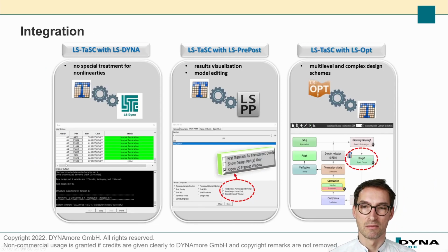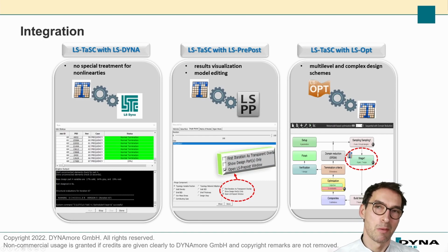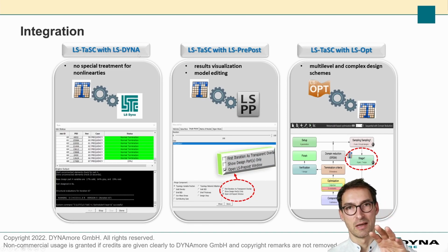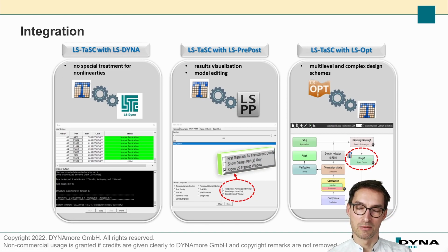LS-TaSC is integrated very well with LS-DYNA because it's the same company, of course. Then we have a very good integration. So LS-TaSC works with LS-DYNA. So you perform an LS-DYNA simulation within the iteration, in the optimization loop. Then LS-TaSC tells LS-DYNA what to do, what to optimize, what kind of model to analyze, and then they have this loop.